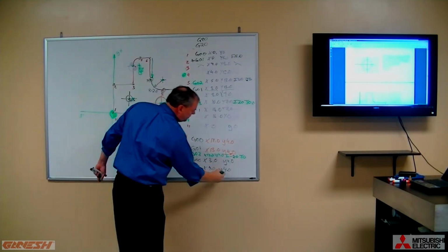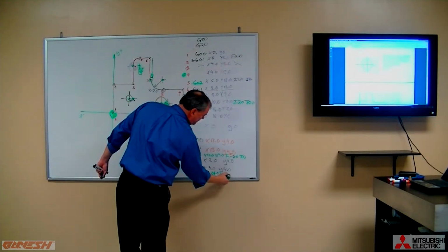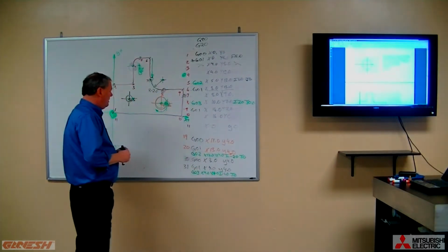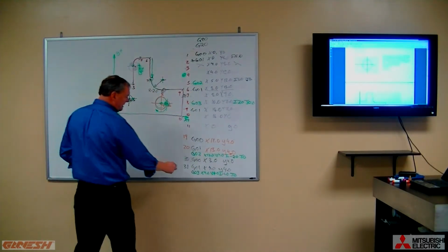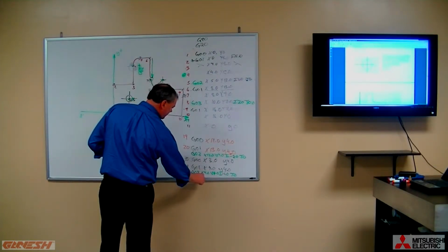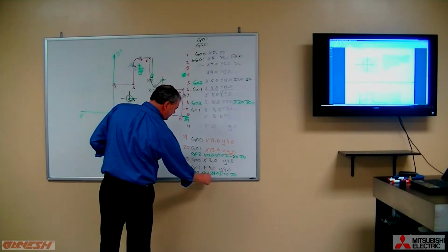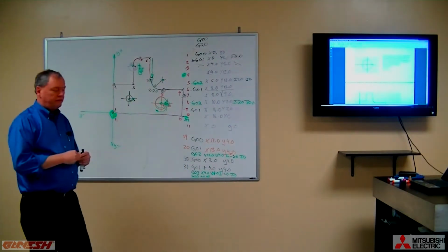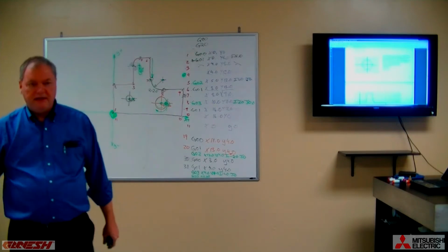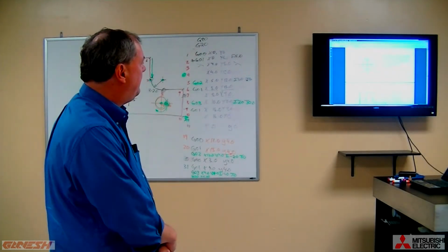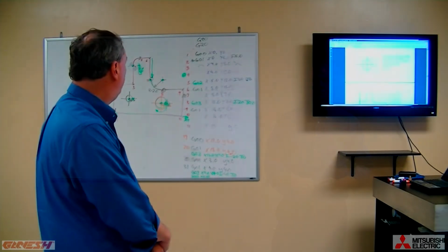Minus 1, it's a 1-inch radius. And we're at J0. And then we probably want to make another last rapid move that says G00 and go back to X0 and Y0. Take us back to there. And now we have the makings of a part program for our sample part that we left off with.